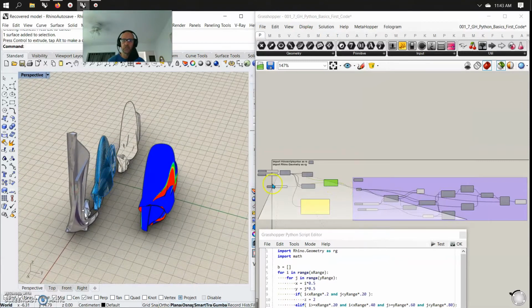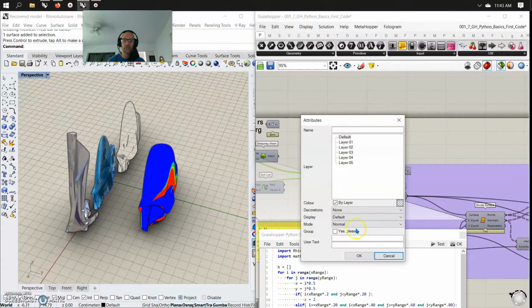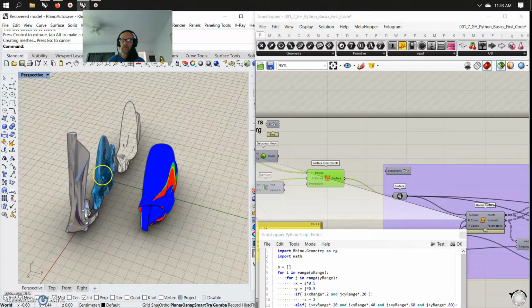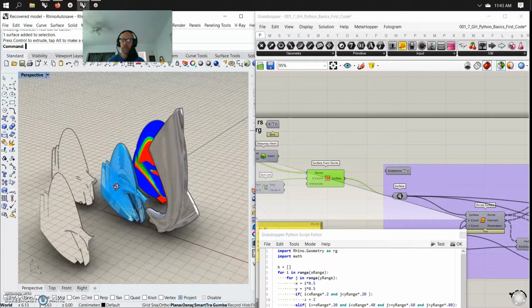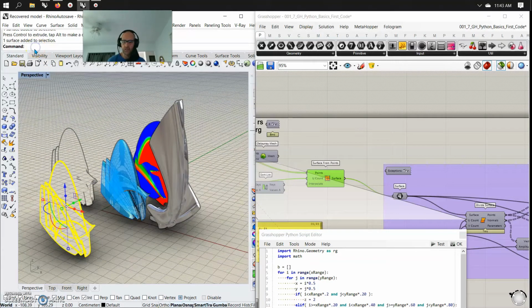You can take that surface out and bake that, and I'll just do that one more time because I know I did it pretty fast, at least in my mind. Let's take a little bake. Let's grab that surface. Let's slide it back over here, and at this point, you could take that surface and throw that into an extrusion through offset surface again. So I'll just do that again in Rhino. It's up to you to decide if you want to do that.